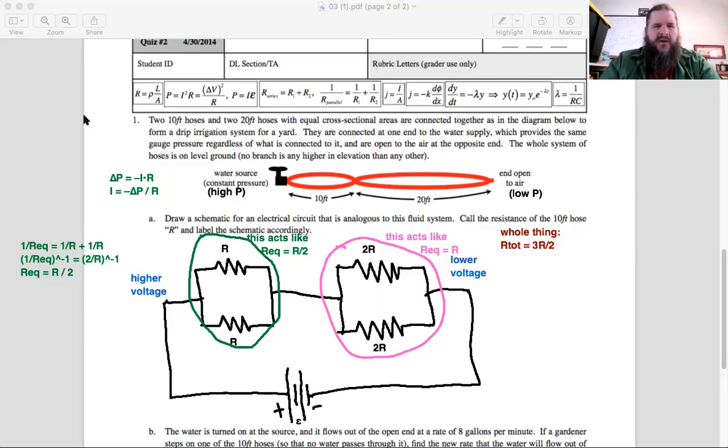And the current, if you know the total resistance, we can just use the loop rule, the simplified loop rule. Again, delta V for the battery plus delta V for the one big resistor is 0. So that's our usual epsilon plus negative IR equals 0. And then we solve for I, and specifically this is going to be current through the battery because it splits when it hits the junctions.